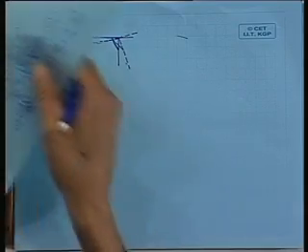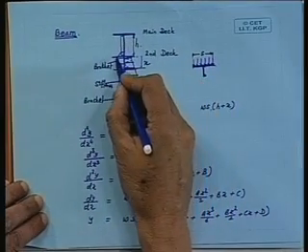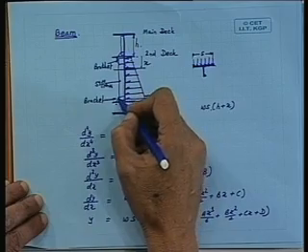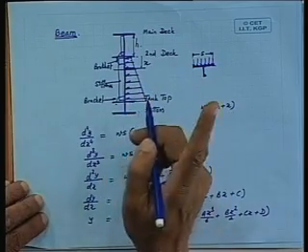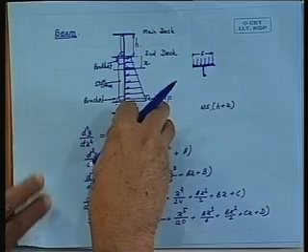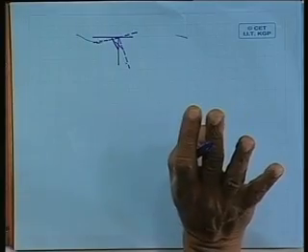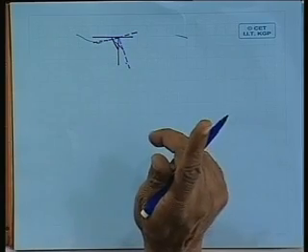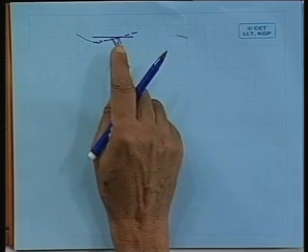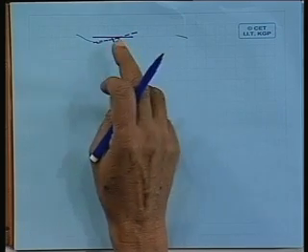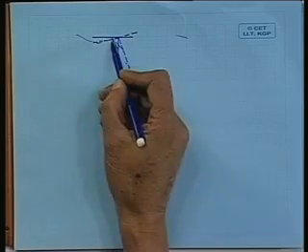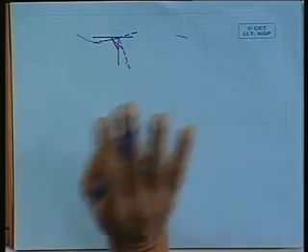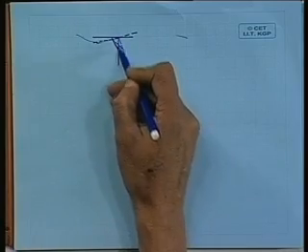Now, this is what is important here: by providing the bracket it becomes rigid, but at the same time the structural configuration is such that it does not behave like a rigid connection. Here we differ from the standard boundary conditions, that the slope is 0 or the moment is 0. As you can see, there is some slope, it is not 0, but the joint remains 90 degree, so both the conditions are being met here.